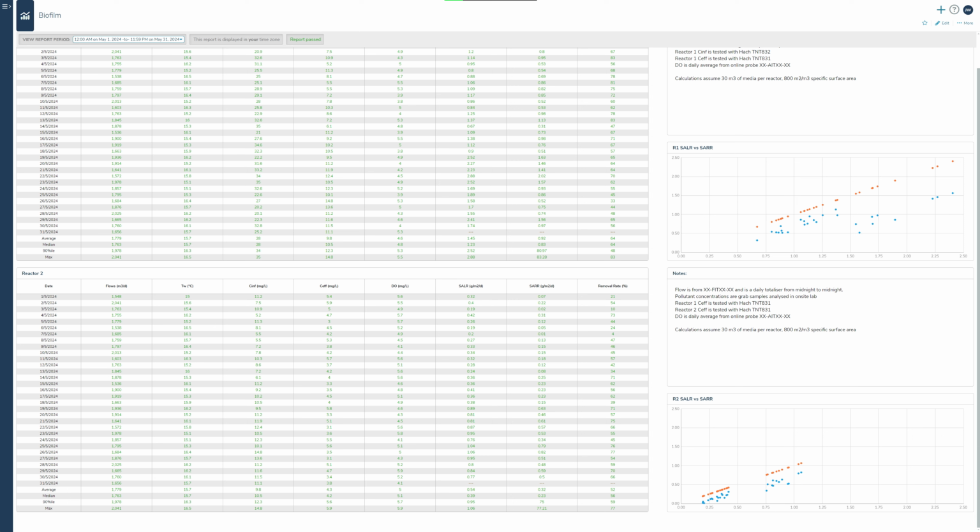And then we can basically say that a layer deeper is, well, how much surface area do you have of media? So then that's the grams per square meter per day loaded onto the system, so a surface area loading rate, and then what is actually being removed, so the grams per square meter per day that's being removed, which is a surface area removal rate. And we can do a DO concentration, so we can estimate where we're sitting and where we're performing based on just empirical data that we have around how these systems should be performing, and basically identify whether the system is being overloaded, whether it's actually underloaded and it's not performing for various reasons.